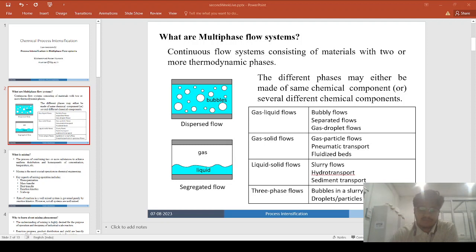So as discussed, the reaction and separation stages are combined together. The reaction and distillation take place within the same zone of a distillation column, and the reactants are converted into products with the simultaneous separation of the products and the recycling of the unused reactants. Among the suitable reactive distillation processes are esterification, nitration, transesterification, condensation, and alkylation.